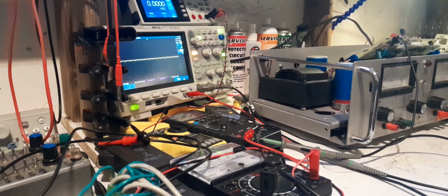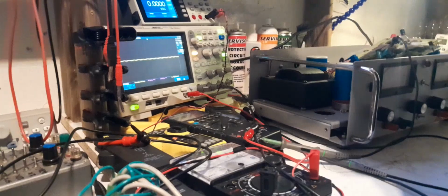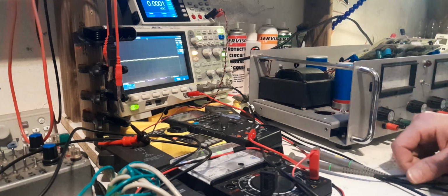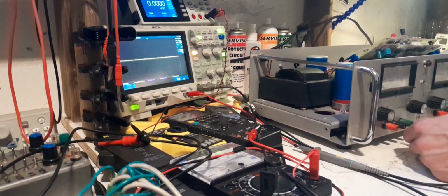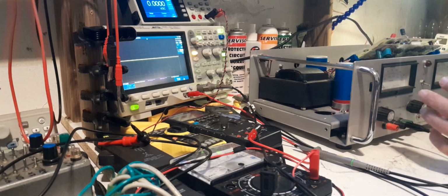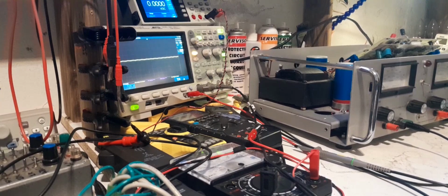Something else I tried doing last night, as I was saying before, I've destroyed the op-amp. I was just about to show you guys what's going on with it. Last night, I was trying to compensate the TL431, like I said. If I try high frequency suppression or snubbers, I get absolutely no effect. If I put an electrolytic on there, I get an effect.